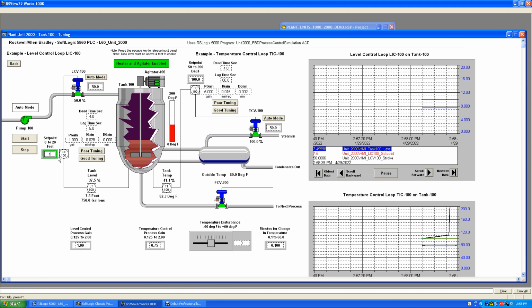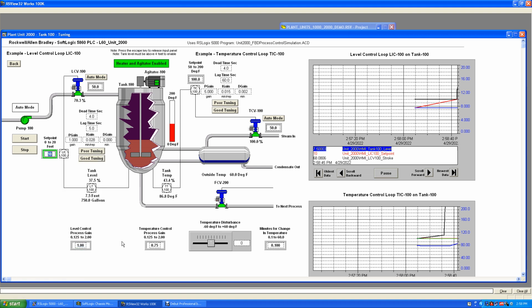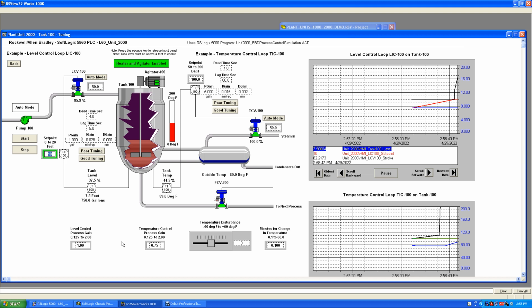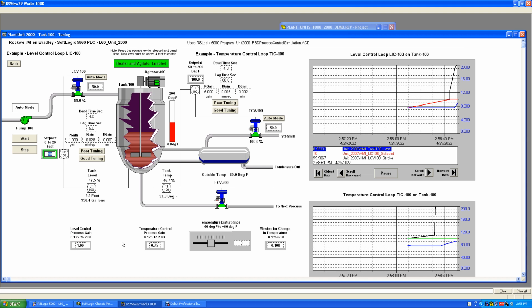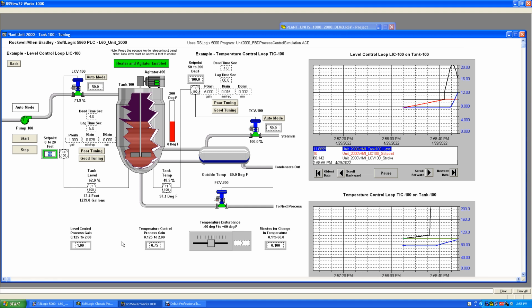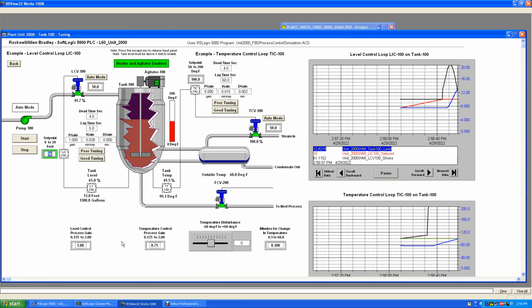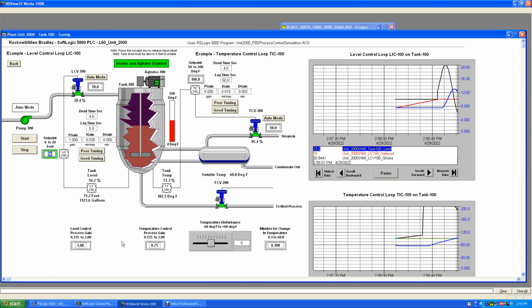10. Then you'll see it'll start oscillating again, because right now it's steady. At manual we set it steady to 7.5 and it was steady. So now we made a set point change to 10, and now it's poorly tuned, so now it'll start oscillating.